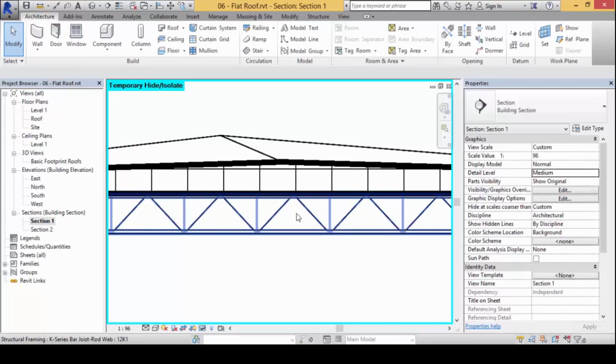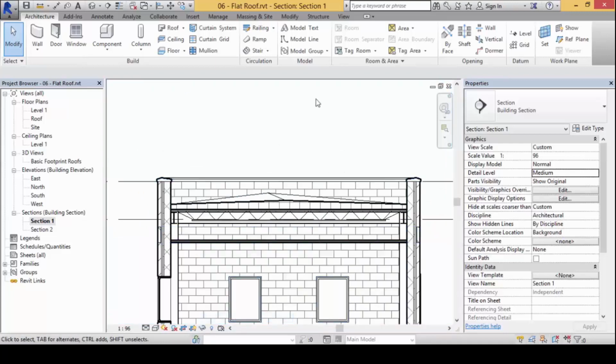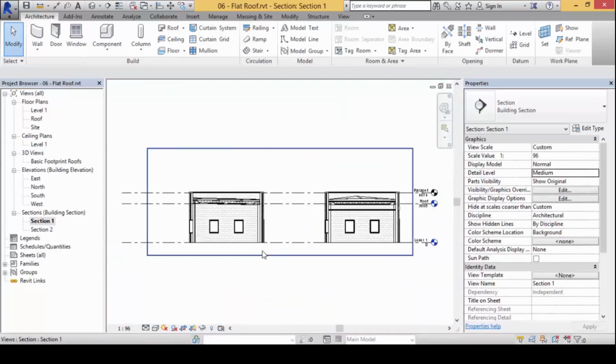This is an exaggerated example. In reality, if you remember, the ratio is 1:200. For every 200 mm you will see 1 mm of gradational difference. If the roof is 200 meters long, only then will you see 1 meter of difference. So that fall is actually pretty gradual. Once we're done with this, I'll just reset the view again so you can see this. Alright, that's how we deal with flat roofs. Okay, so we will close this now.